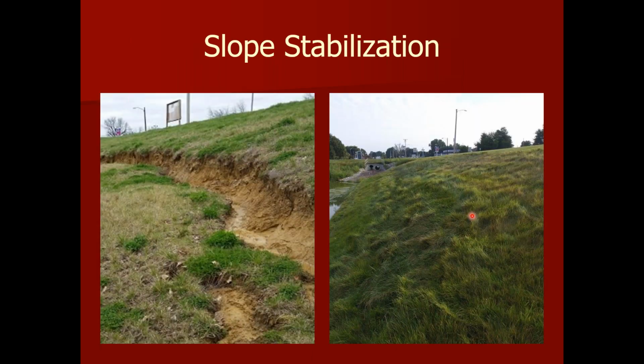Slope stabilization, you can see here on the left an area where there's a typical sloughing failure, probably a pop out, saturation within the bank, stress along the toe of the embankment, and you have a geotechnical stability issue that turf reinforcement mats, a lot of times with the presence of anchors, again, which we'll touch on, can be brought in, regrade that system, regrade that section, and install vegetation to be able to provide the stability here downstream of